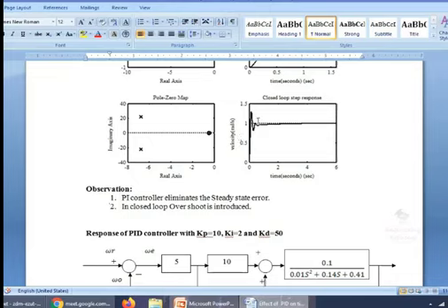Okay. So to reduce the overshoot, what is the necessity to reduce the overshoot? Can anybody say? Why do I have to reduce the overshoot? Let it go. So you think about the valve control. If I am giving the control action P plus I, it is moving to a high peak. Think about the mechanical assembly. If you're going to a high peak, what will happen?